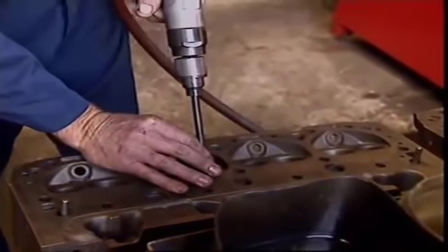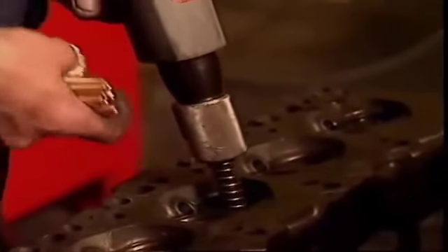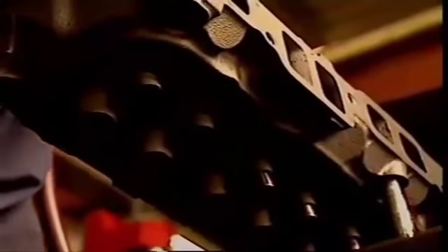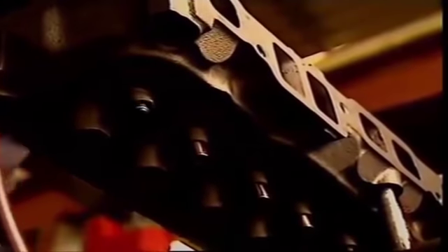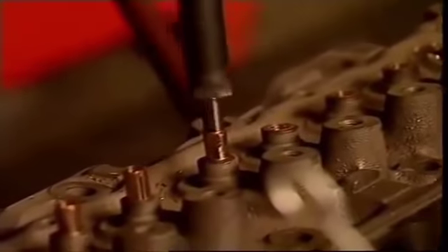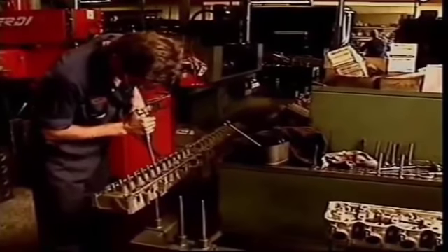Cast iron guides are necessary in aluminium alloy heads to provide a suitable bearing surface for the valve stem. Many heads use replaceable valve guides that are a form of metal bush pressed into holes in the cylinder head. Other cylinder heads have guides cast as part of the cylinder head, then bored to the size of the valve stem during manufacture.